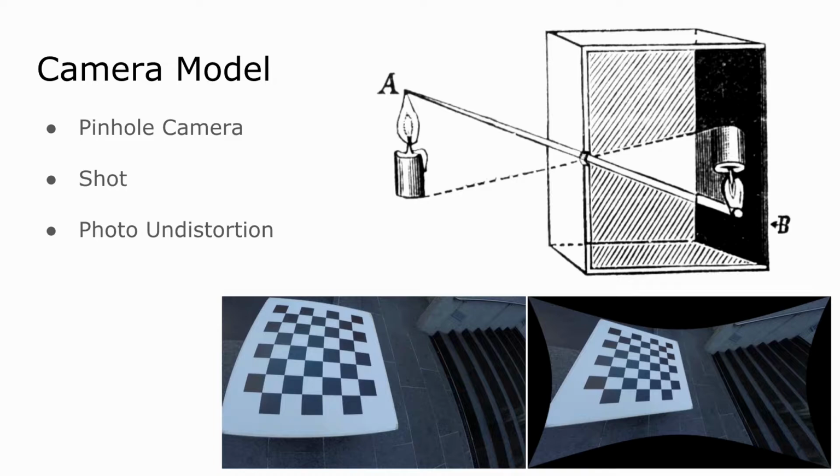Important, if you want to do photogrammetry, then the standard maths is usually formulated in terms of pinhole cameras. So if you have real photographs like this, they have a whole bunch of image artifacts, for example, the lens distortion and so on. So you usually want to revert the real camera to a pinhole camera, for example, through lens undistortion, which takes these curved shapes and makes them straight. There are programs that do this for you for some camera manufacturers, or there are also some OpenCV functions that can numerically do this for you.